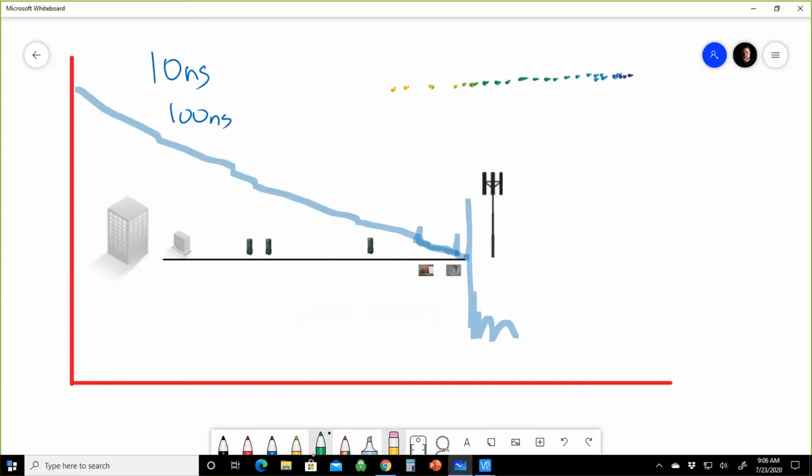100 nanoseconds allows you to see possibly the vault splice, but not necessarily, because it's kind of close, only 100 feet away, right? So it might merge these together, where now you're going to have just one big launch. And within that event, it's going to be the FTB panel and the vault splice mixed in together, because 100 nanoseconds is a very long pulse.